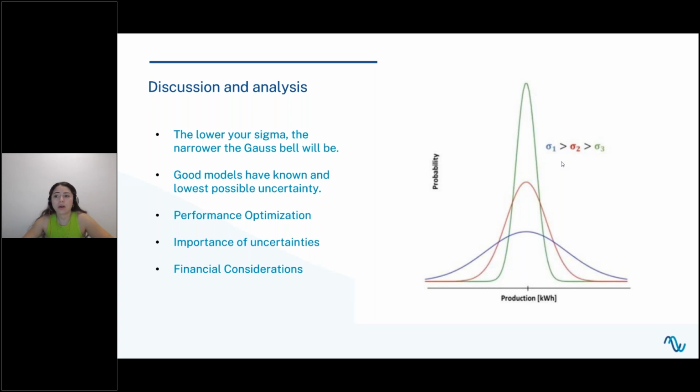So the range of energy yield estimates at different confidence levels, the P99, P95, P90, and P75, will provide insight into the potential revenue variation and financial contingency that need to be considered. So as a summary here, incorporating uncertainty into the energy yield calculation through pvDesign as a tool will enable the stakeholders to conduct comprehensive risk assessment, optimize system design and performance, and make informed financial decisions.